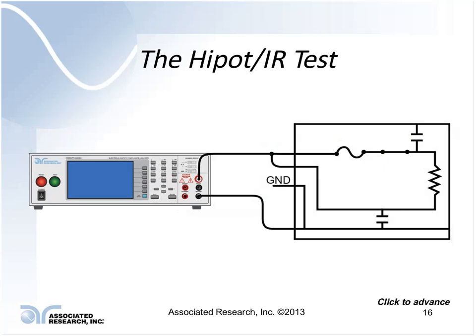So what's happening here? If we represent this diagram as a circuit, essentially what we have here is, you can see we have a fuse. You can still see high voltage tied to plus and minus. And you'll see we have two capacitors. I've simulated the insulation as these two capacitors because they're going between your mains circuit and your chassis point. So you have these capacitive values, and sometimes you can even have capacitive coupling to ground when running these tests. That's essentially what you want to measure: the leakage current flowing through those capacitors.